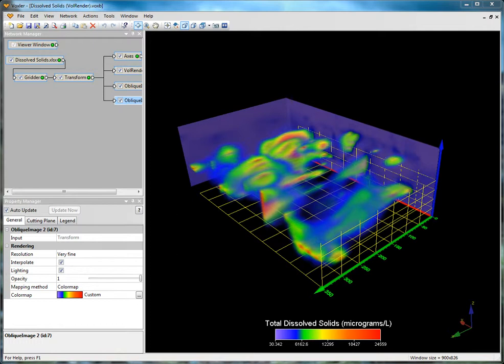VolRenders use direct volume rendering to display voxels directly on the screen. A voxel is a volume pixel, the smallest distinguishable box-shaped part of a 3D image. Volume rendering is a three-dimensional display of data that simulates the transmission and absorption of light through the points in the volume. Light rays are cast through the volume, where the particles within the volume simultaneously emit and absorb light. The color of an individual pixel on the screen is computed by compositing the contributions from each particle intersecting the ray. This allows visualization of inhomogeneity inside objects with appropriate adjustment of the opacity.